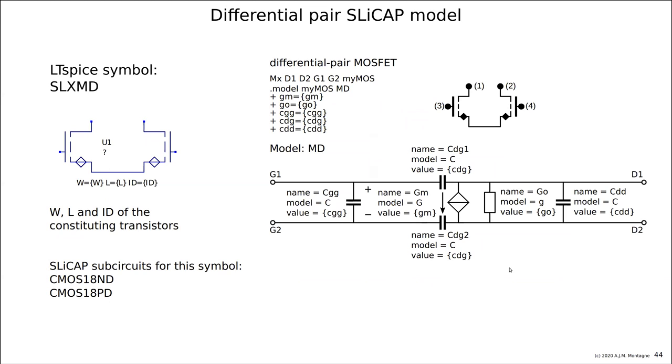Later on, when we are going to talk about negative feedback and put stages in an amplifier, and we want to calculate the loop gain, we need a reference variable, a control source to select as reference for the loop gain. And if we have a differential pair with two control sources, then you can never take the differential pair as a whole as one stage.